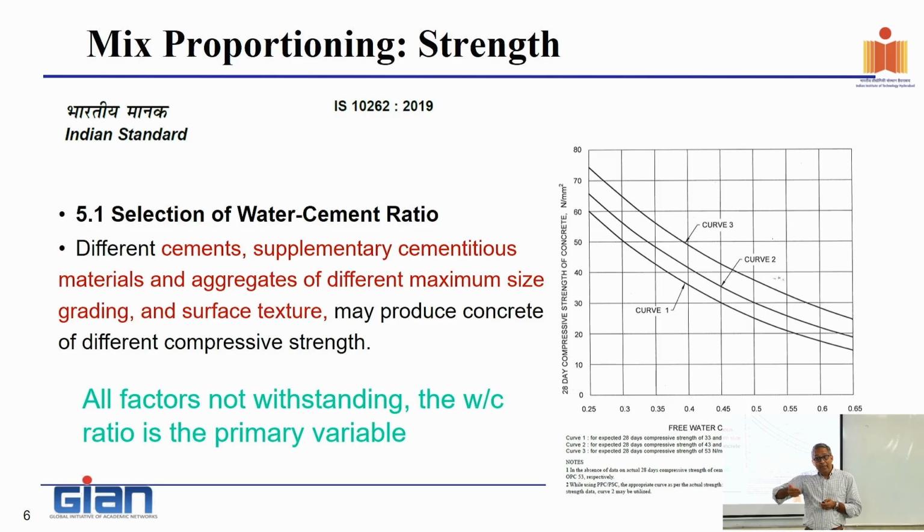Now, my cement content in the concrete would go up, right? Because I'm fixing the proportions by masses. Let's say 40% of the concrete is going to be paste, 60% is aggregate. What defines the cement content in this 40% of paste is the water to cement ratio. If the water to cement ratio is low, cement content in the concrete will go up.